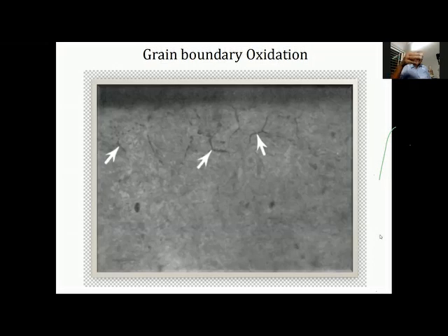And that's why we use, in fact, the oxygen probe for control of the carbon potential, because there is oxygen at ppm level at least present in the gaseous atmosphere. But this should not exceed about 12 to 15 microns in a typical integral quench furnace. If it is more than that, then there is an issue with the control system or maybe leakage somewhere in the furnace chamber. We go to the next.